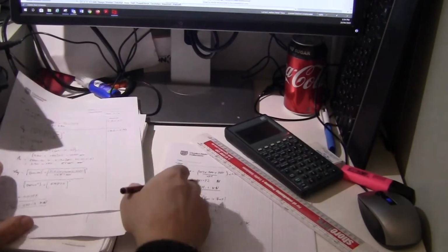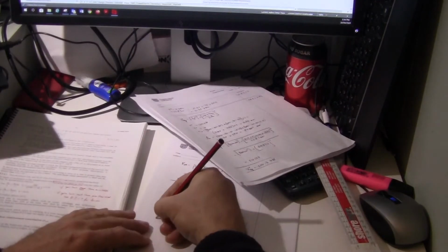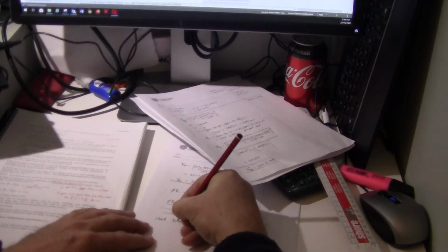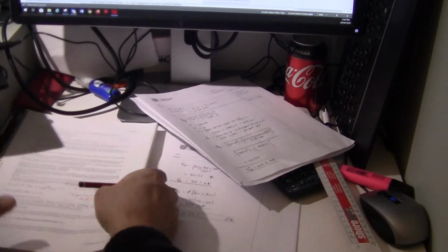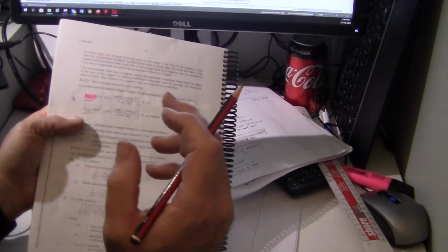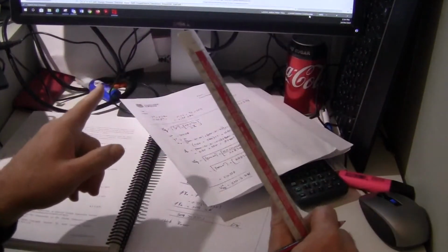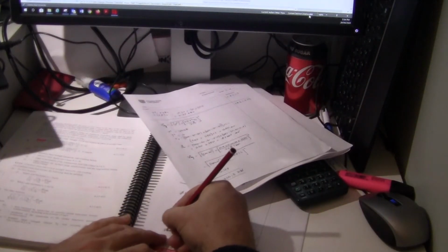There's a couple more things to tie up before we get there. First, we have to check VU max. VU max is back here. If the concrete is not large enough and this whole thing collapses, that's limited by VU max, and no amount of steel you put in there is going to fix that. That means you cannot take the capacity of this beam as anything greater than VU max.